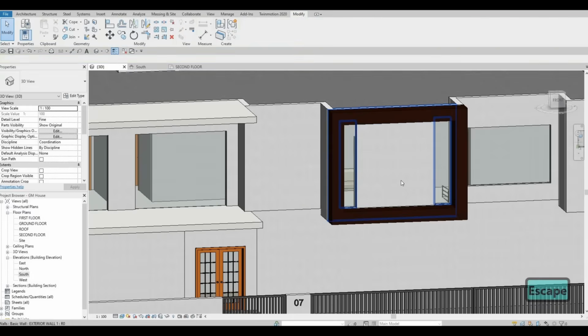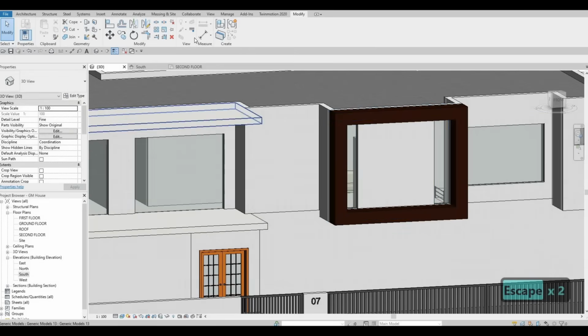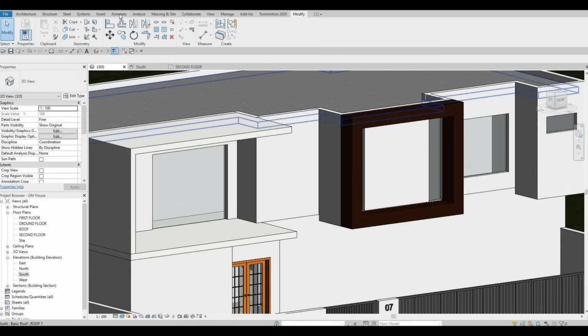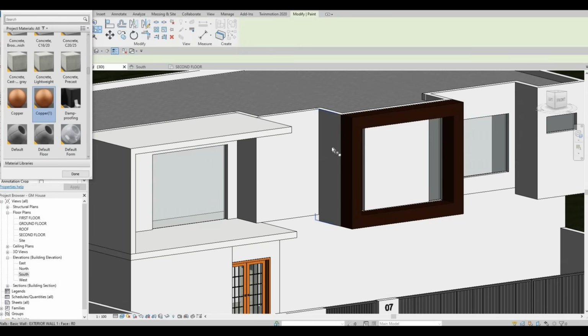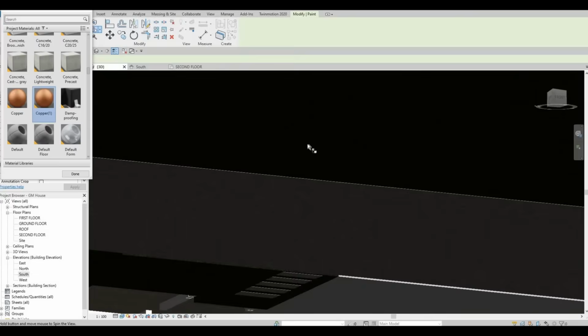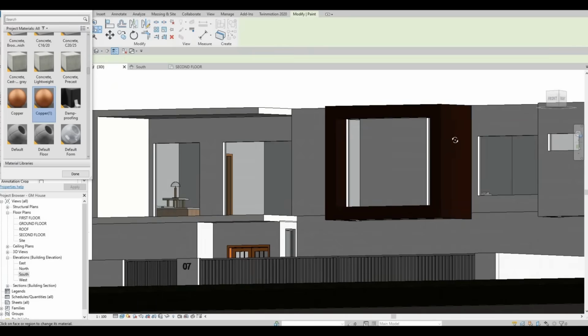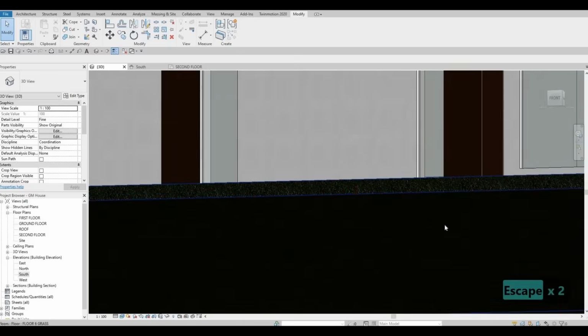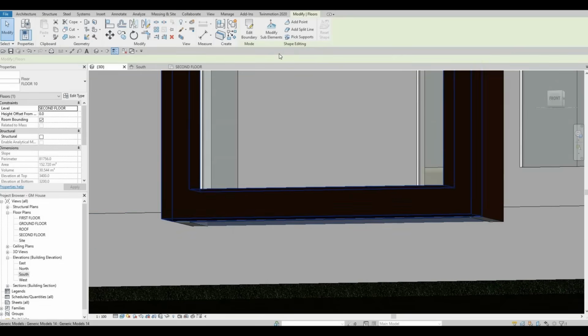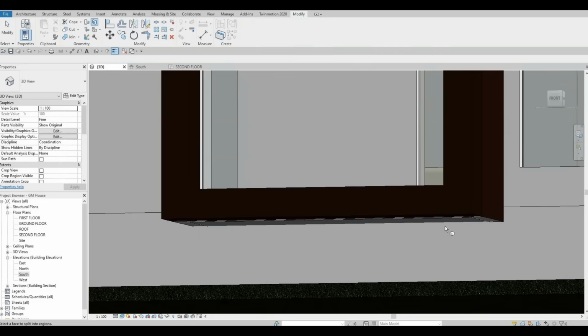And then here we could select the copper, same. So what we could do is select the copper on this face. We need to go to paint, and then look for the copper one that we created. So copper one, add this face right there on this face, and here the one below we need to basically split face this.